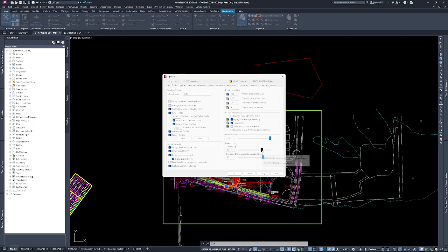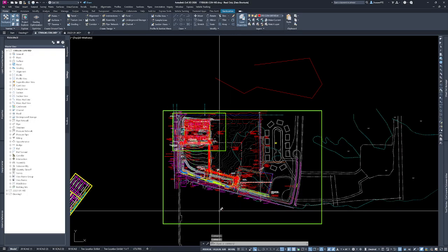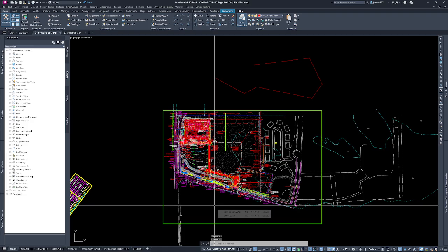Now, the issue I'm running into right now is the problem with this. This is a CAD setting, not a drawing setting. So the next drawing I open, all my XREFs are also faded, which, okay, that's fine and dandy in some cases. But I also have multiple XREFs, and it does it for all XREFs. So if you have 3 XREFs in there, it's going to fade all of them out. That might not be what you want.